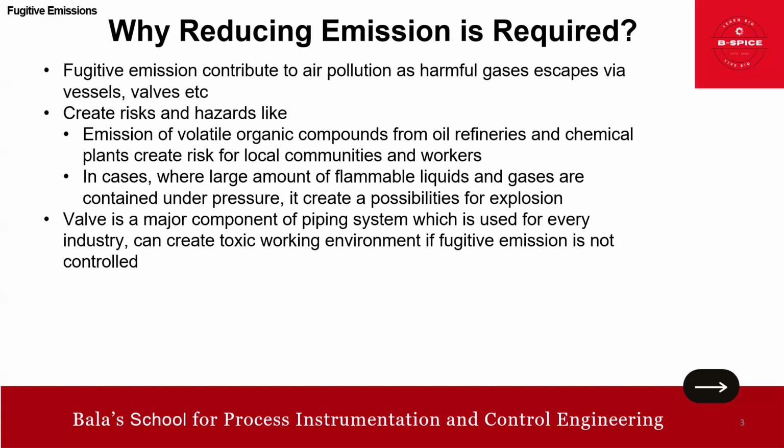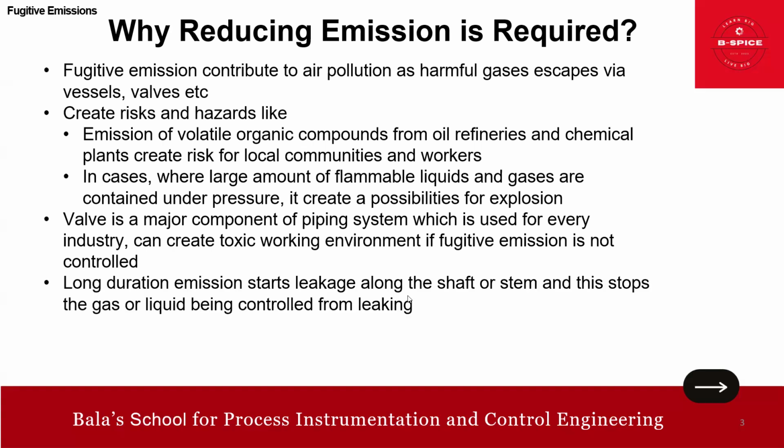And valve is a major component of the piping system, isn't it? So it's used in every industry, right? So it can create a toxic working environment if fugitive emission is not controlled, because of the leak through it, and human operators will also inhale it, and that will cause a lot of health issues, all these, right? So long duration emission starts as leakage along the shaft or the stem.